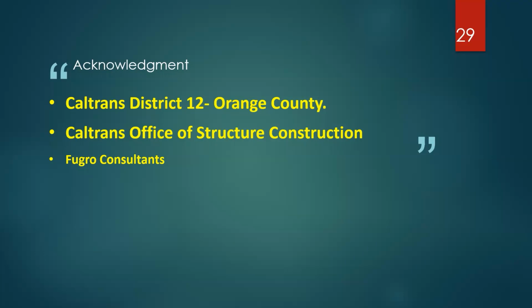But the PDA tests were done at least one and sometimes two for each bridge structure because of the control zones, and some of you who've done this are aware of that. And CPT again was an excellent tool to capture the difference between the control zones and establish the number of PDA tests for each bridge, which we did. So there is that as well.